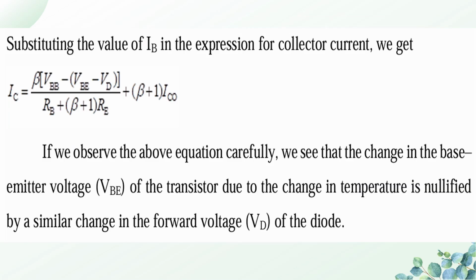If we observe the above equation carefully, we see that the change in the base emitter voltage of the transistor due to the change in temperature is nullified, because the effect of increase in VBE will be cancelled by the subtraction voltage VD.